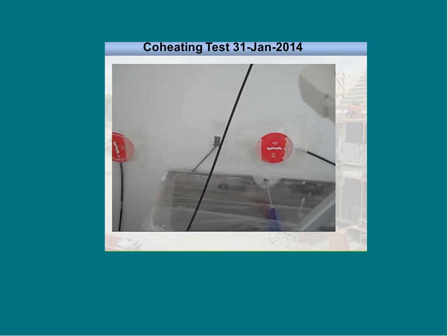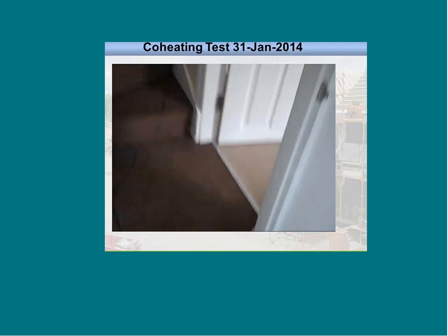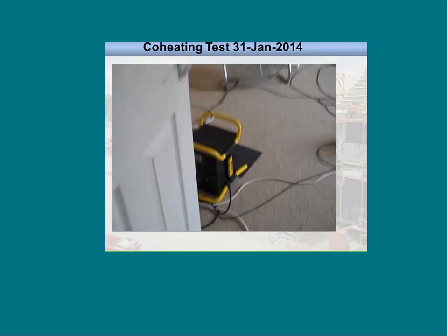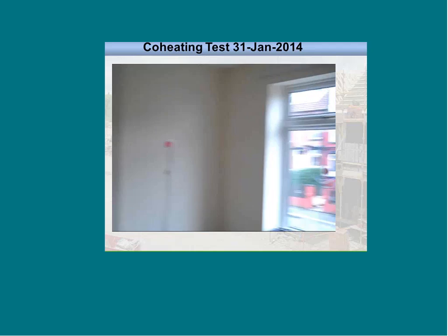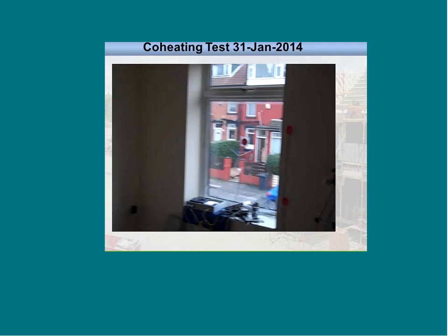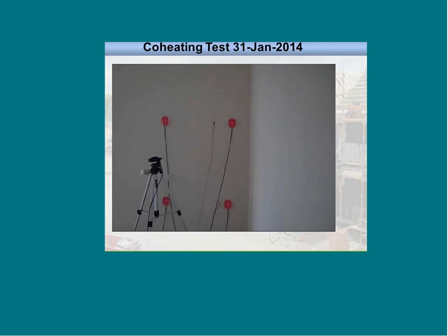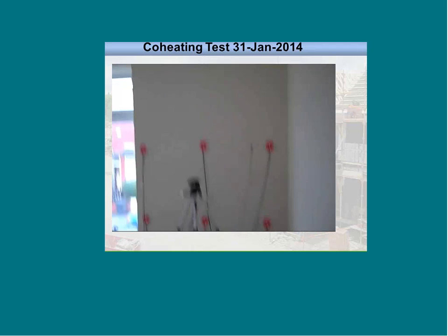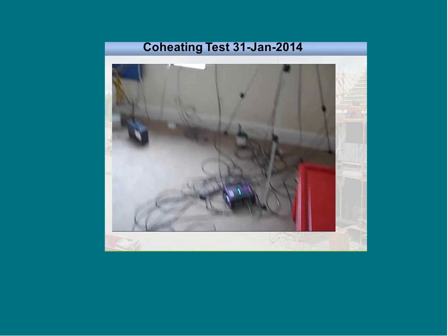So you see the thick red line indicates the intersect of the 3D surface with the QH delta T plane. And from this we see a layered flag hanging downwards. The layers in this flag indicate the discrete values of the daily averaged values of the solar radiation occurring during the coheating test. The advantage of this method is that we can read from the graph the heat loss coefficient as the upward slope of the regression line. Additionally, we can also conclude something about the solar aperture coefficient as the fraction of the traversed heating power and the traversed solar radiation by looking at the outline plot.